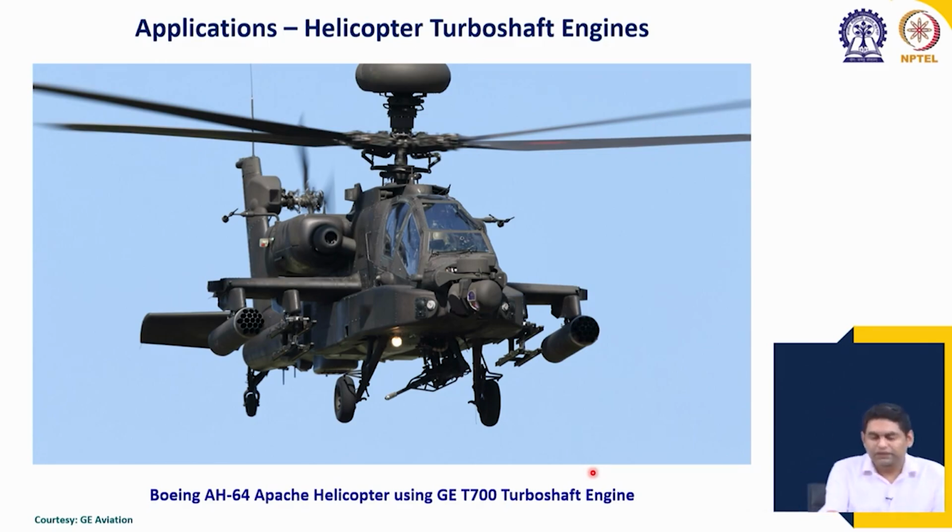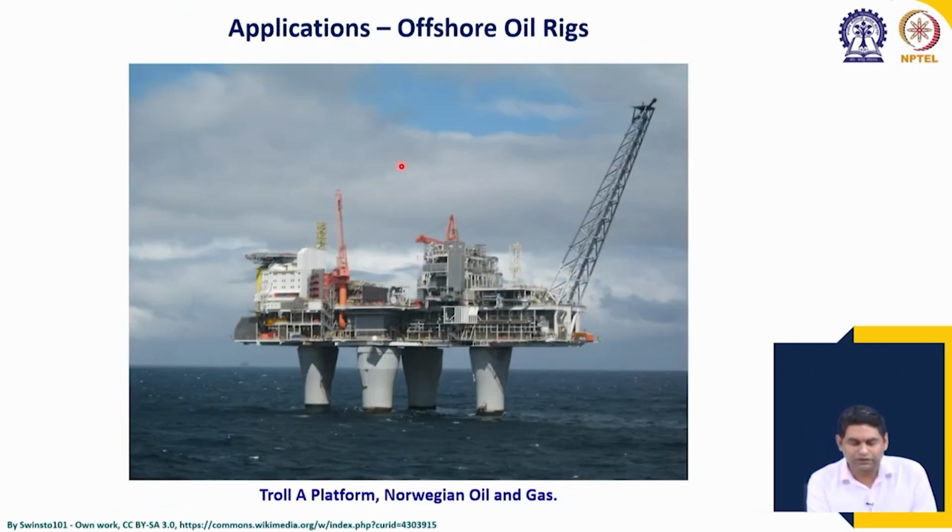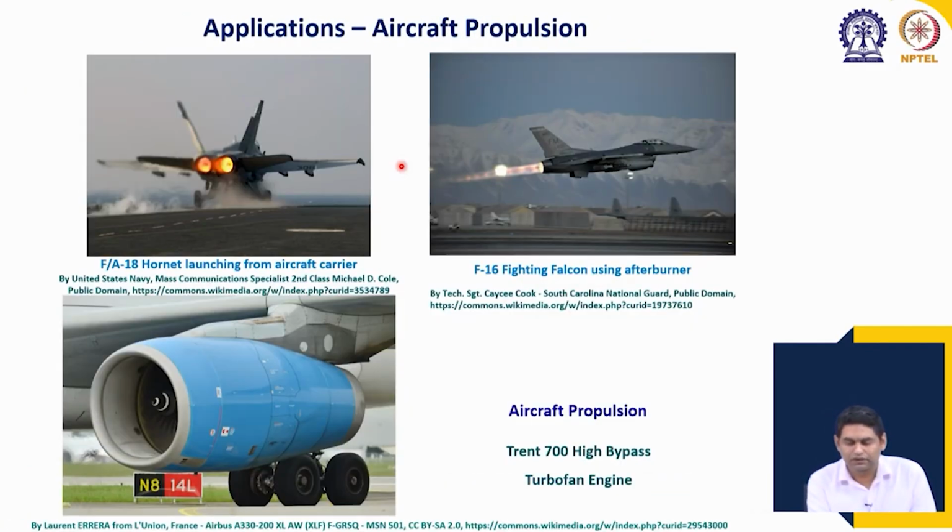Okay. And by changing the direction slightly for the propeller, you can create even forward thrust vectors, and directional thrust can be generated. Okay. So, here the propulsion is not done by using jet propulsion, like in the previous jet engine cases. There, the propulsion is done by propelling the exhaust gases at very high speed through the nozzle, and the role of the gas turbine is to run the compressor, so that the combustion occurs at high pressure, and we have a very large pressure for expansion in the nozzle.